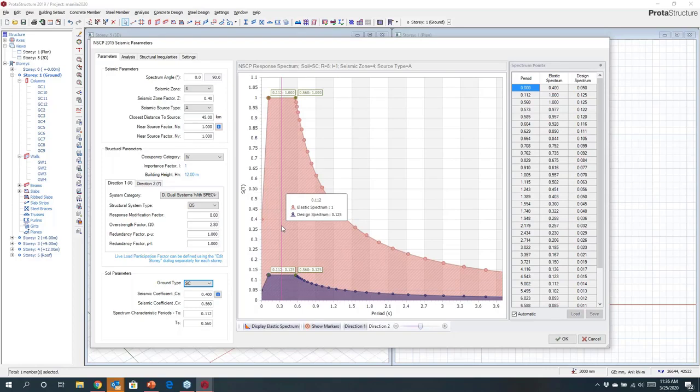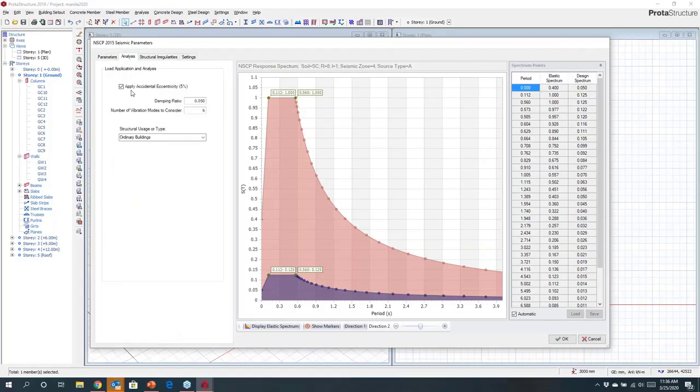If you wish to key in your own parameters here, you can. Okay, all this is flexible. You can even import your own seismic spectra if you've done a site-specific study. These can be brought into the software here. Now, during the analysis, we will automatically apply the loading eccentrically, and damping can be set. Okay, so typically for concrete that will be 5%, but you can set other values if you wish. Okay. Now you can also choose a number of modes that you wish to run.